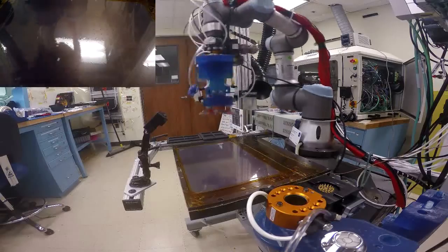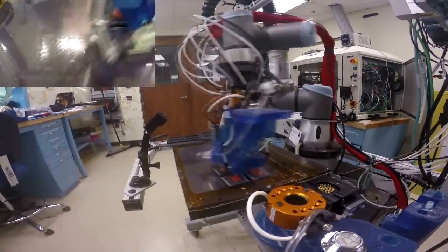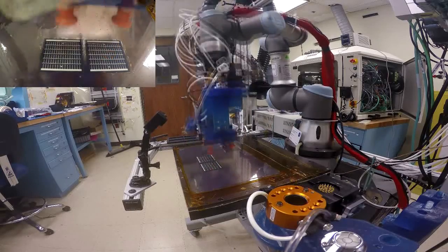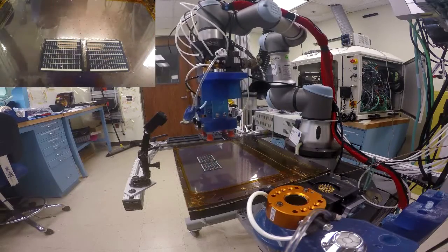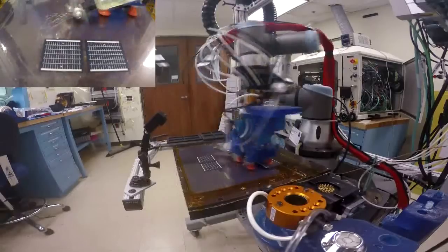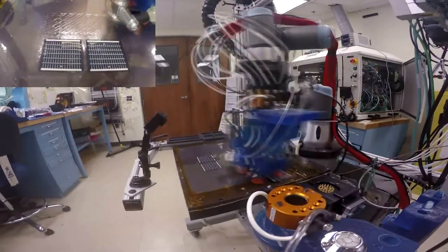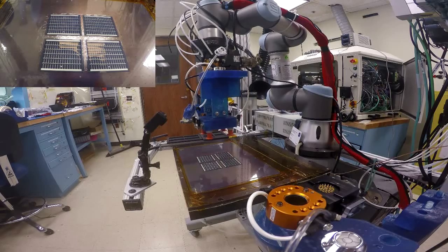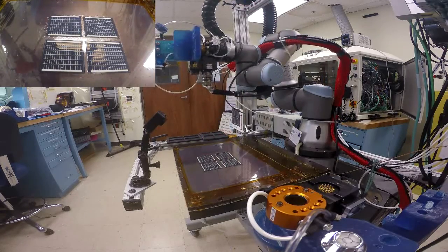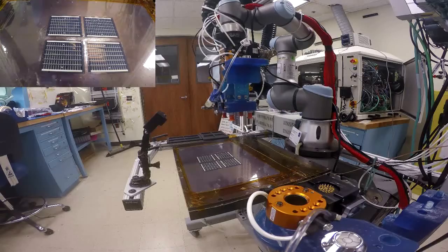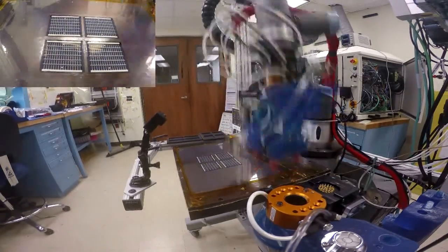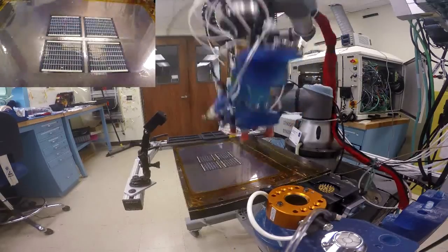I've got slides to break this out, but what you're seeing now is we picked up solar cells with our pick and place tooling, and we're actually laying down an adhesive. Now, this isn't technically a third-party adhesive, which I'm going to reiterate later, but we spray it down, and then you can see we drop the cells right in place where we need them. So this actually embeds the cells into the top layer of a polyimide substrate, which you can see down there on the platen.